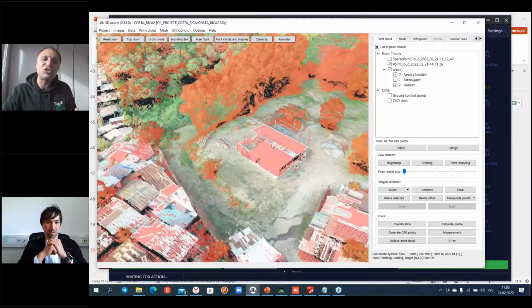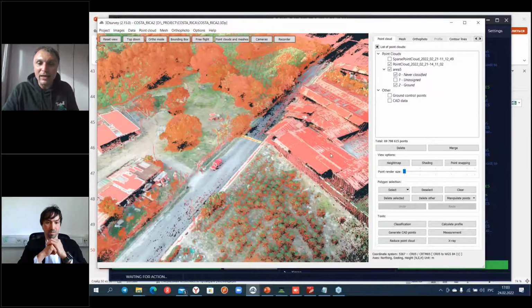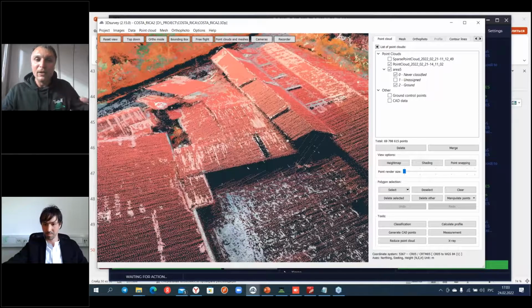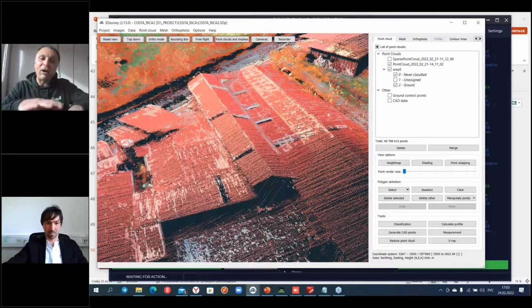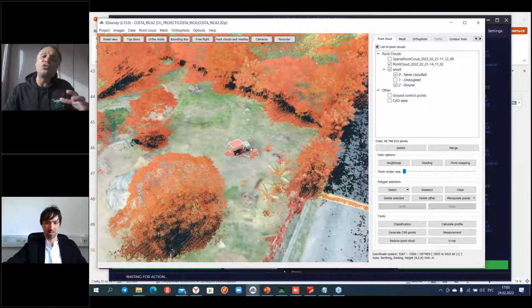And this one, it's a major advantage of 3Dsurvey. It has very precise photogrammetric point cloud calculation. And after that, you can add your LiDAR data like this one, and you can see that the LiDAR data totally overlap the photogrammetric data, and all of them are aligned together without any problems. And of course, I don't do any correction in coordinates. It is due to the very precise post-processing and very precise aerial triangulation.